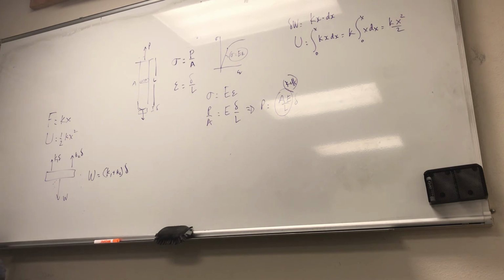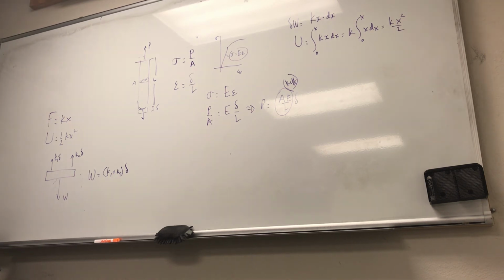Imagine you have this vertical piece in here that is pinned right at this point, and then you push with the force F. You can probably guess what's going to happen: this original thing is going to rotate a certain angle. That means that for this spring, you cannot say the springs are in parallel or in series, because they don't share the same force, nor do they share the same displacement.